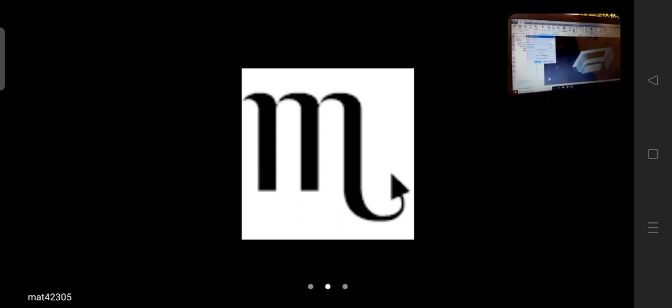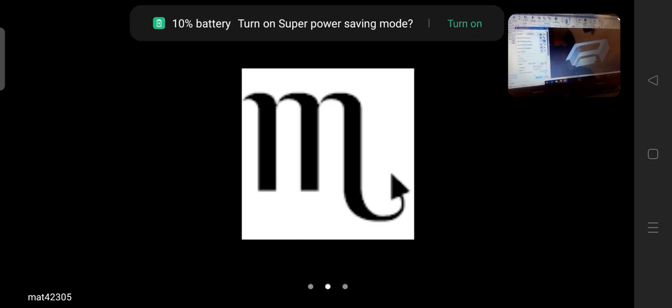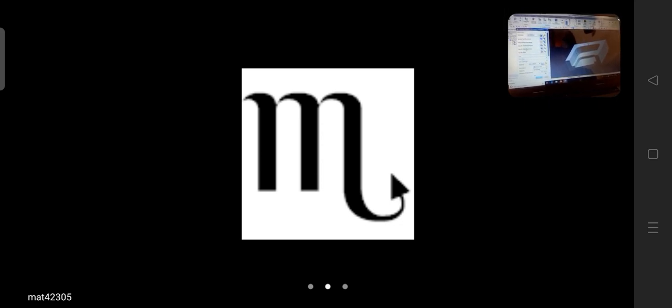Okay, now one thing, let me see. Don't click OK. Change the type from closed to open, and click OK. Okay, then click OK again. Now that is it. Now click on the bottom option called specify floor. After specify trim boundaries, you will see specify floor. Yeah, that one. Click on that.